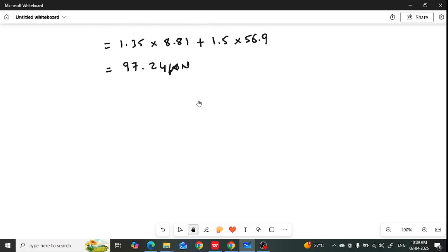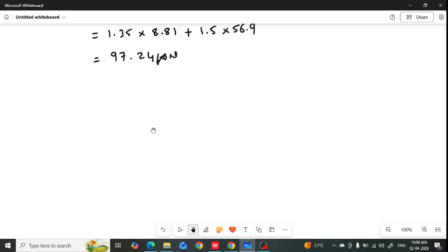Now we need to check the effective depth of slab. We have provided the effective depth of slab. See, the overall depth of the slab is 250 mm, and the effective depth we can extract from that is 220 mm. So we need to check whether the depth of the slab that we have provided in the bridge is okay with respect to the strength criteria or not.